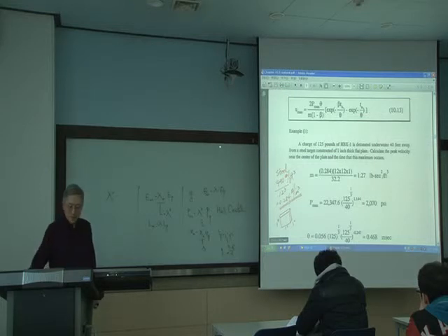So here is the mass per unit area. Steel is usually 490 pounds per cubic feet. You can get this from the handbook, or you divide it by 12 cubed, because 1 foot is 12 inches.